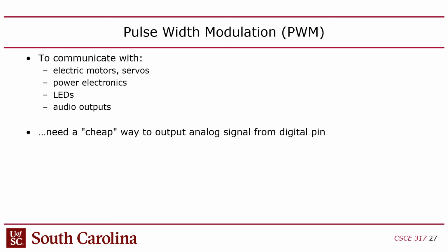But that signal has a duty cycle, which is the percentage of the period that the signal is high, which is set to be a percentage of the VDD value, right? So in other words, a PWM is basically a periodic signal that has a switching frequency, or a period, which is the repetition length, right? The length of the repeating pattern. The period. And the percentage of time that the signal is high within that period can be multiplied against the VDD voltage, and that will look like the analog value over long stretches of time, right? So in other words, let me show you that.